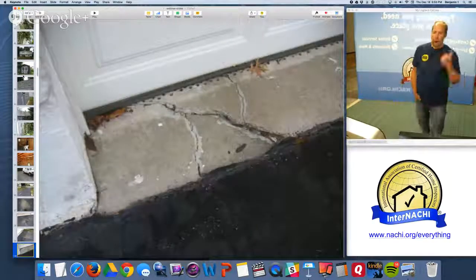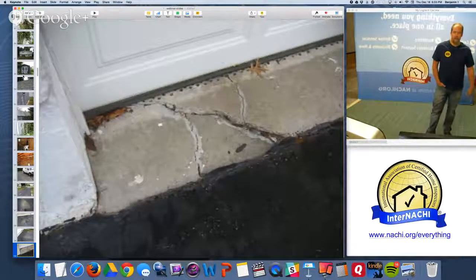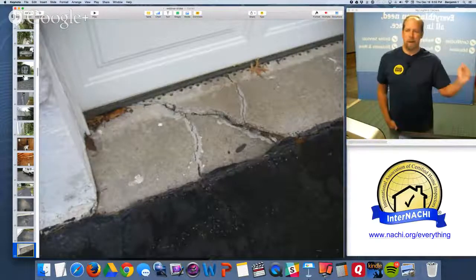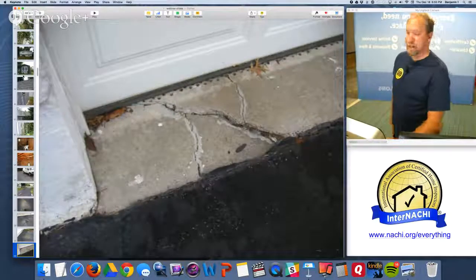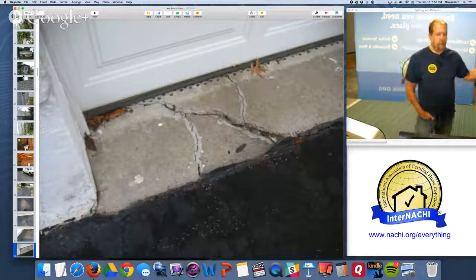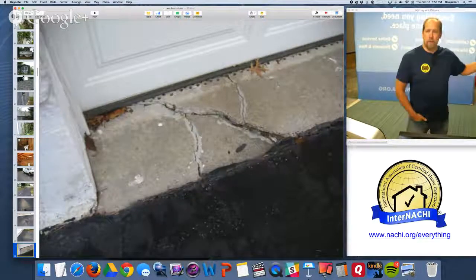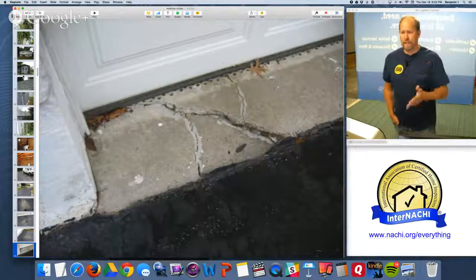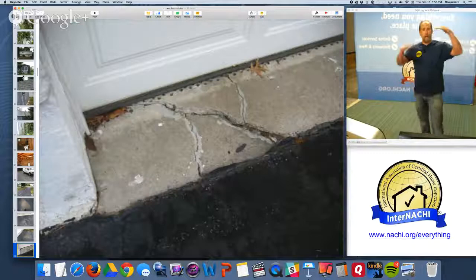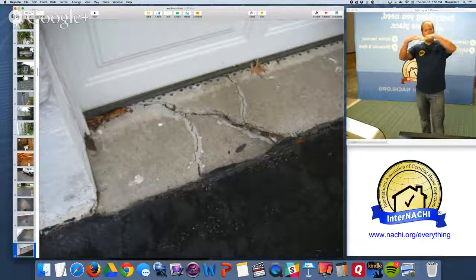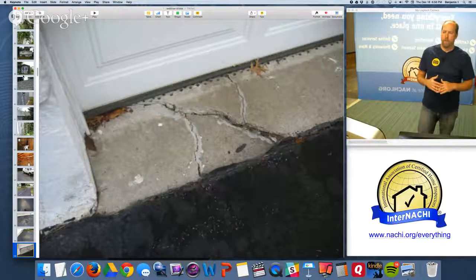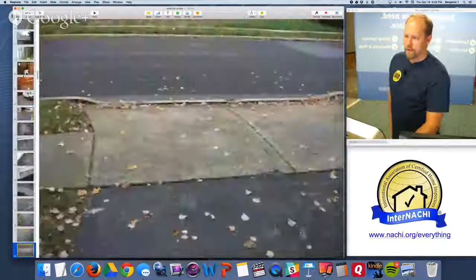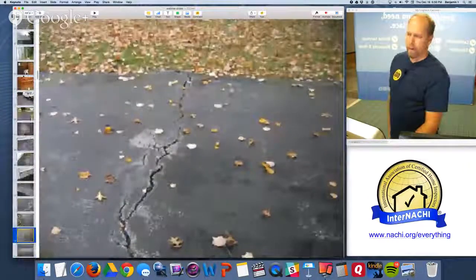Water has popped that front threshold area of the garage door, and they've drilled holes, drain holes, all along the front to catch it. I don't know why they just didn't do a trench, a French drainage trench with a metal grate, something. There are many different options to fix this problem where the driveway may be higher in elevation than the garage floor, or it could be sloped in, where there's a negative slope towards the garage. Driveway's in poor shape. Some of the roots are popping up.